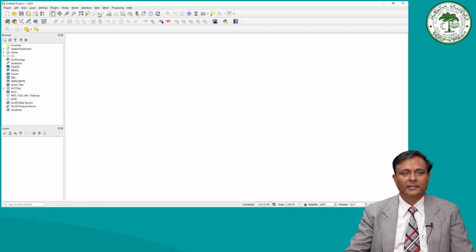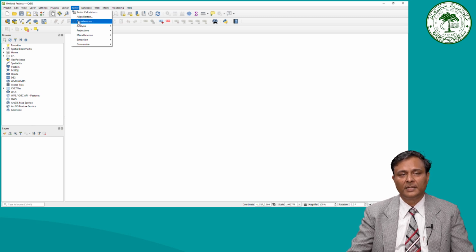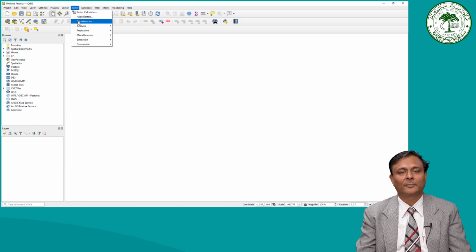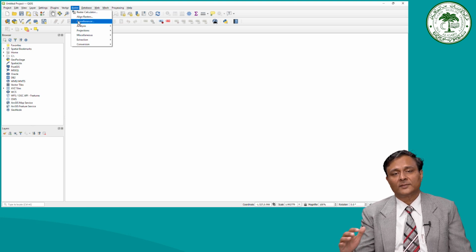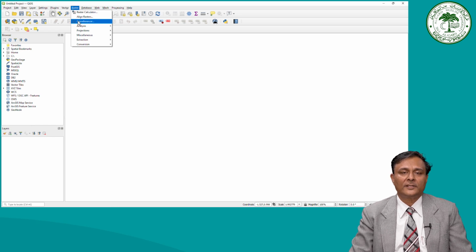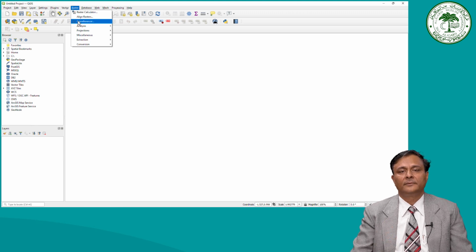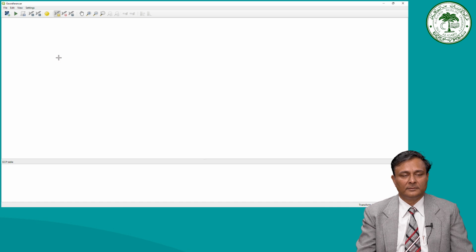First I would look into the raster data, and I would be using a new data here. I would georeference it. It is a topographical sheet map, and I am georeferencing it again for your benefit so that you can learn, because on the previous occasion we georeferenced where the latitude and longitude were in absolute terms. Today we would be georeferencing with decimal digits also. So that would be a new learning for you as to how you can georeference with decimal degree coordinates.